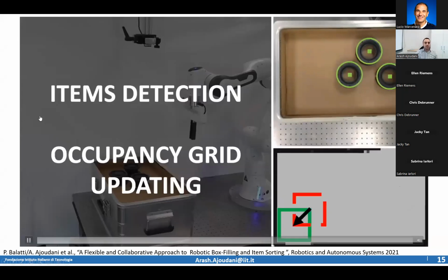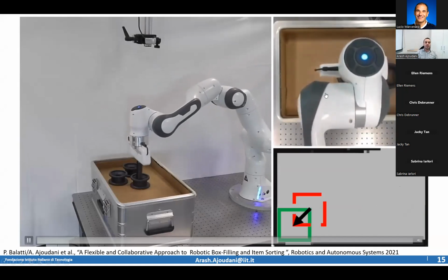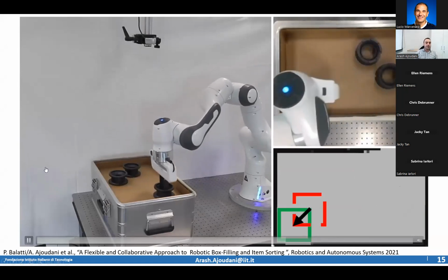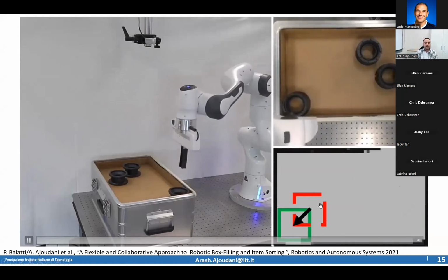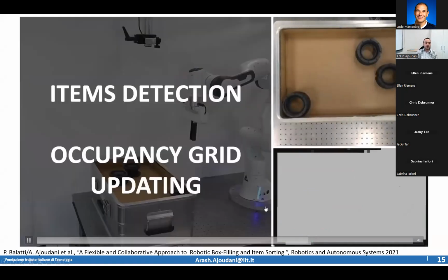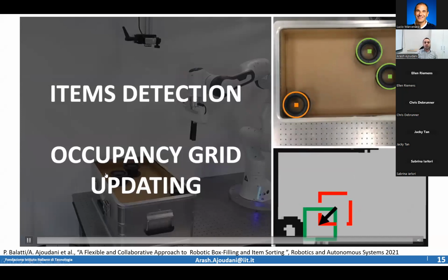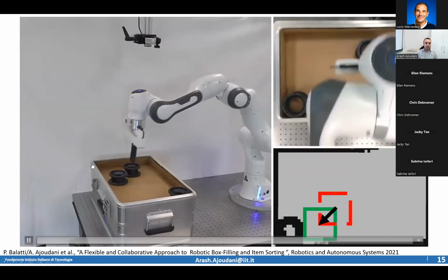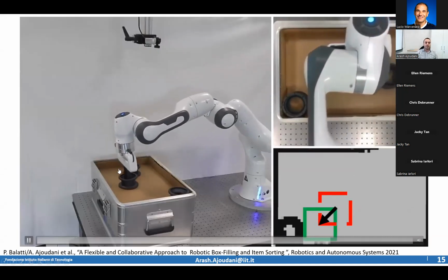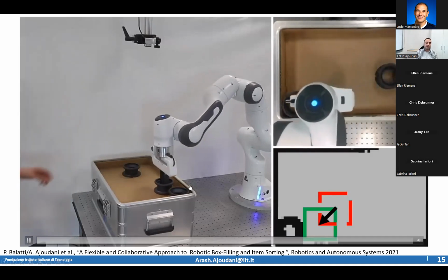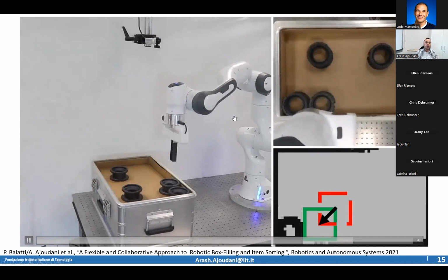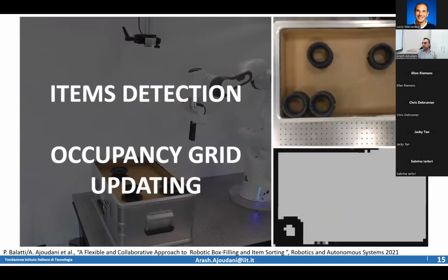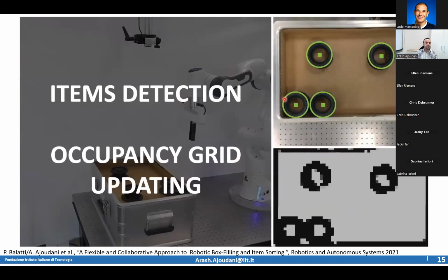We replicated the same strategy in object resorting. Imagine you have objects in boxes, and you want to resort them. Again, you can define a strategy. This is my desired pose, and you balance between how much confidence you have from vision, with its uncertainties, and how much confidence you have from the force tracking. Again, this will let you comply with the disturbances that you have from the system. Let me go to the laser pointer, yeah.